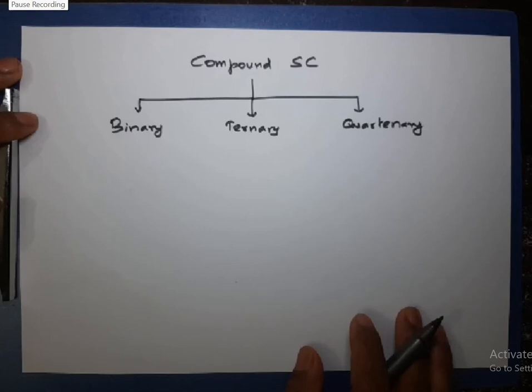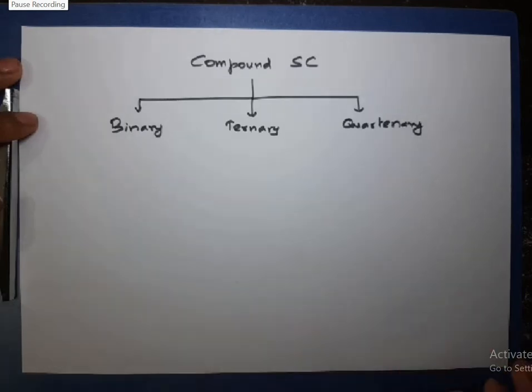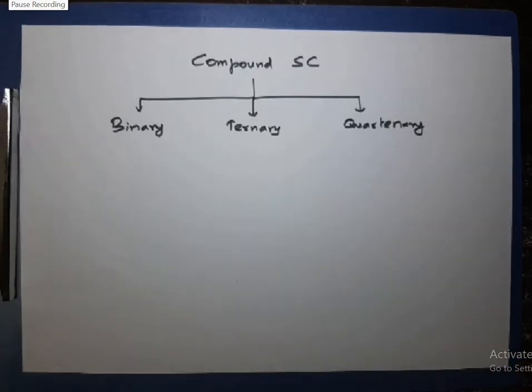In the last lecture, I discussed some important classifications of semiconductors, that is, elemental and compound semiconductors. Then we also discussed direct bandgap and indirect bandgap semiconductors, and I mentioned one important point: in a direct bandgap semiconductor, when a transition takes place from the conduction band to the valence band, the excess energy is released predominantly as photons.